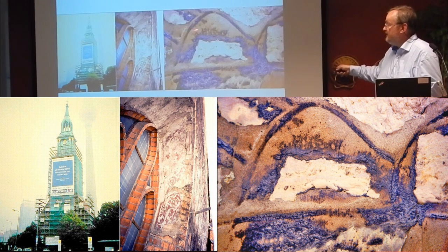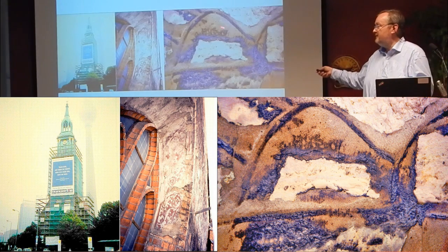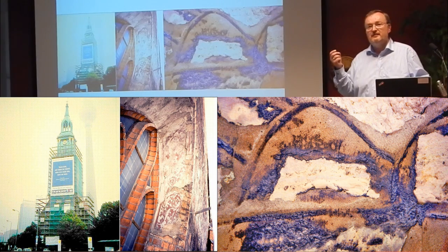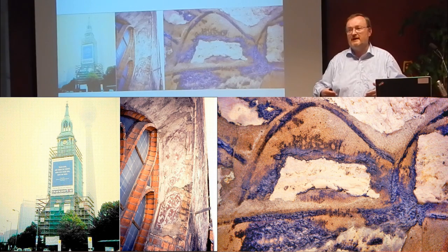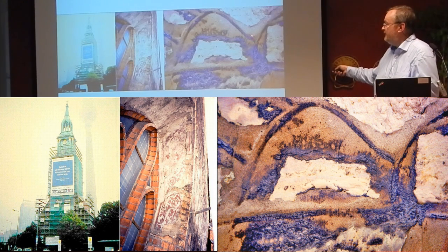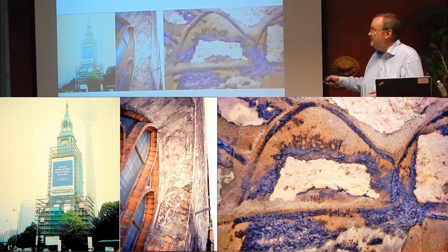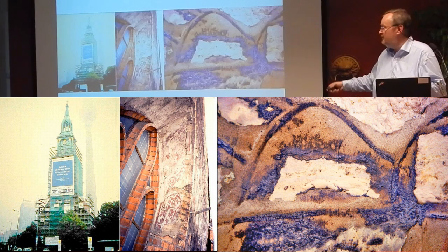And this is cementitious mortar done in the 80s when they had repairs at the facade of this tower, and they did not have the money to make the Baroque rendering on the whole tower. So they decided to have joint mortars in a very crazy shape, and water comes in and takes out a lot of crusts and residues and things like this, and we managed to repair this. We will not throw away the cementitious mortar.